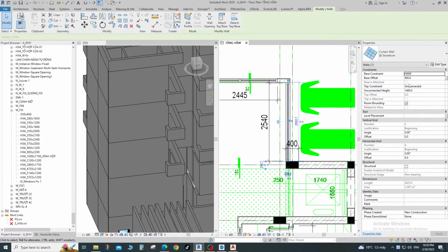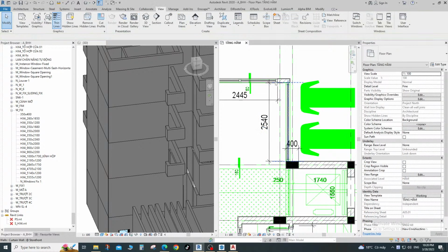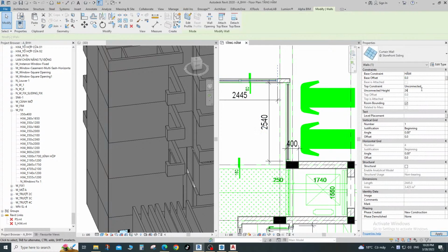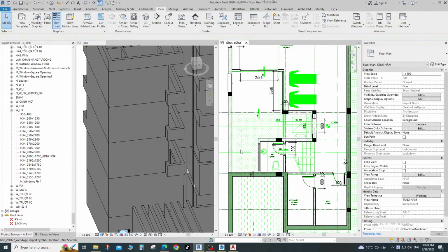Let me try in 3D view. We can't do it in 3D view, so let's go to side plan. I'll just place a column with that rod, and okay, add grids, so one here. I'm going to just place one first. Okay, so place, oh hang on, 1 2 3 4 5. So maybe just select all these, 1 2 3 4 5, and also this grid that intersects with all these grids. And then finish. So let's have a look in 3D view.